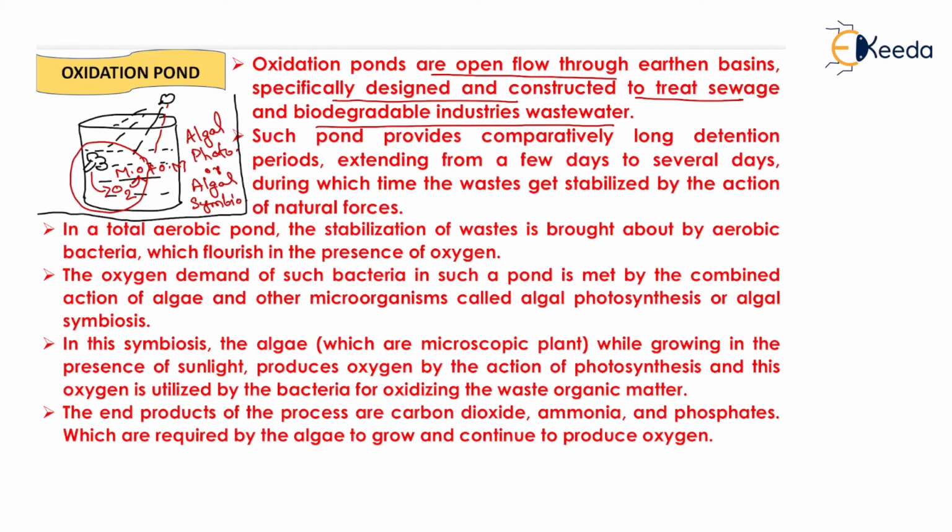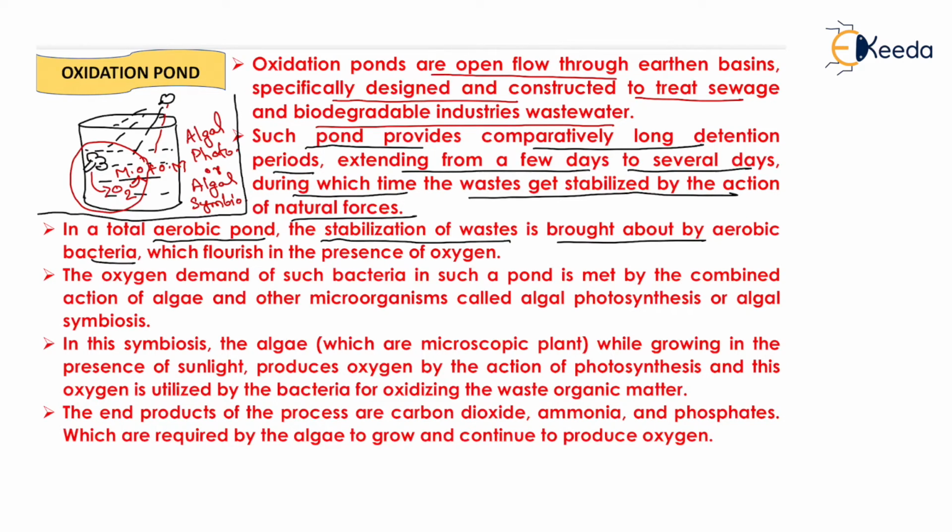Such ponds provide a comparatively longer detention period, extending from a few days to several days, during which time the waste gets stabilized by the action of natural forces. Which type of natural forces? Photosynthetic reactions. In a totally aerobic pond, the stabilization of waste is brought about by aerobic bacteria, which flourish in the presence of oxygen. With the help of aerobic bacteria, we can decompose the organic matter.